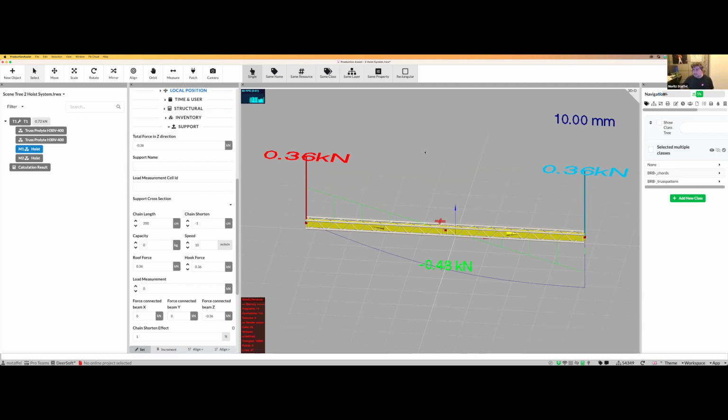There is one limitation I want to point out: this only is true if the supporting legs of the hoist, so basically the chains, are kept parallel. As long as this is the case, it does not change the load on the individual hoists.